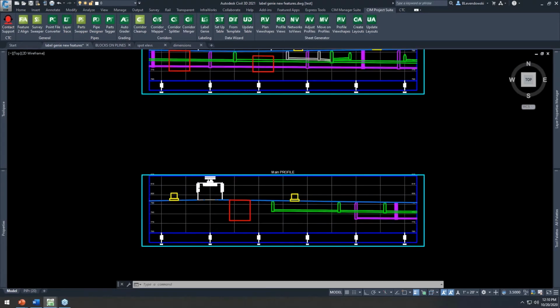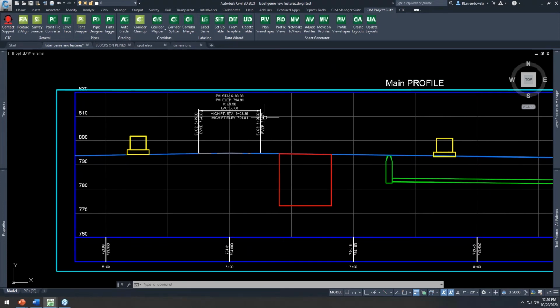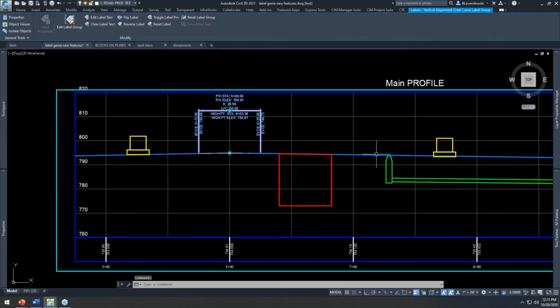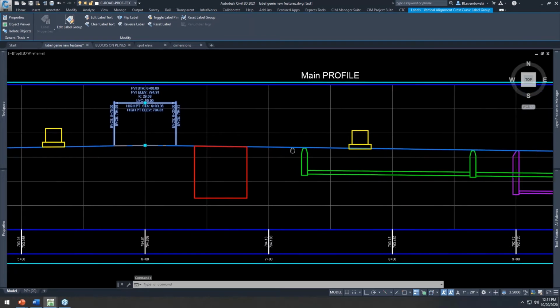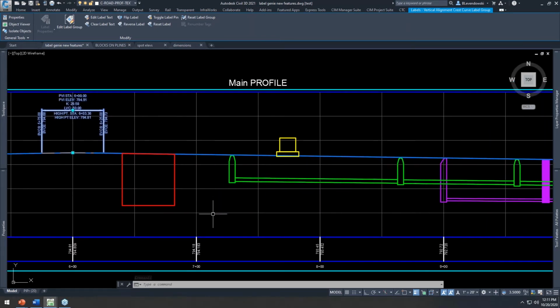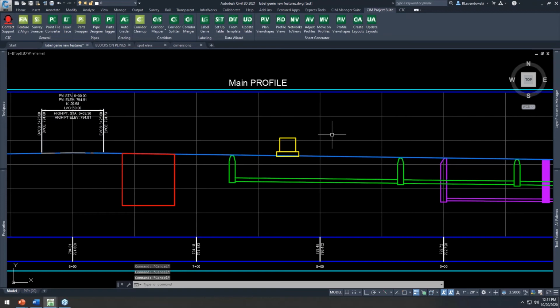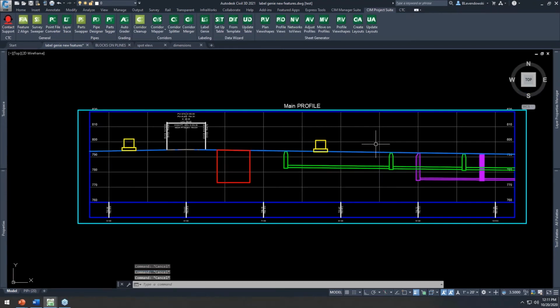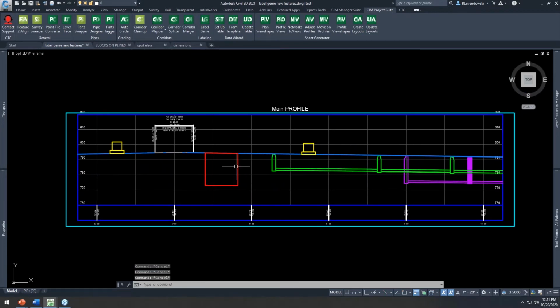Now, a lot of this labeling is automated for us. So we're not recreating things like profile label sets, okay? If you project some COGO points to your profile, you have opportunities there to assign a label. Okay, so we're not recreating some of that stuff that arguably works very well. But what about when we have to do some manual drafting in our profile views?